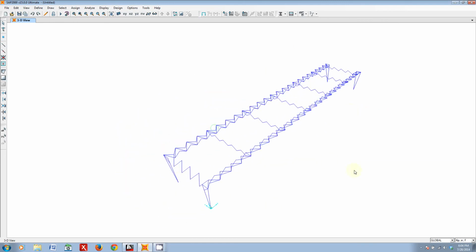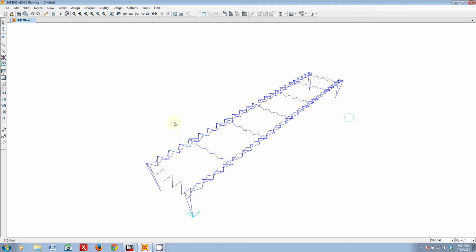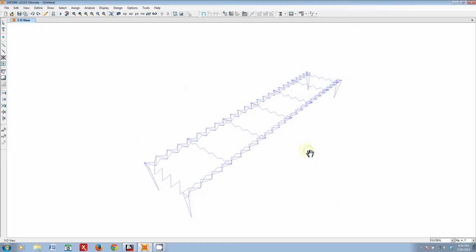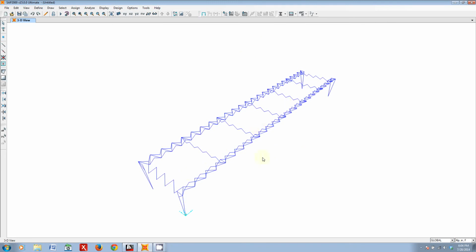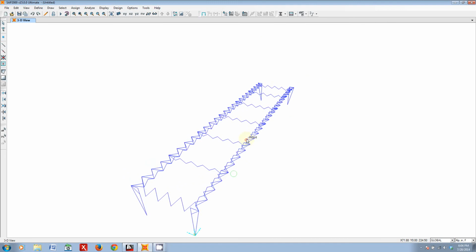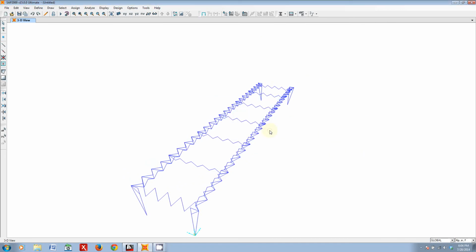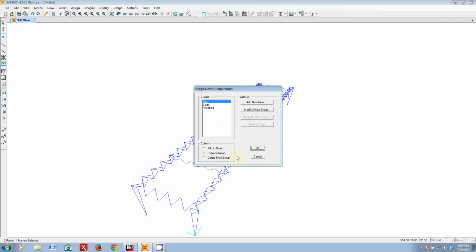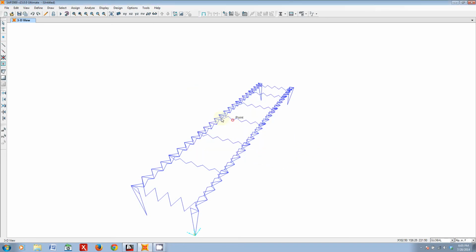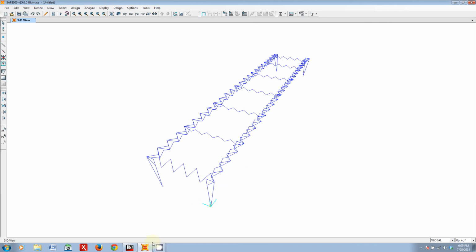But I will upload the final completely imported file into the Dropbox, so you can take a look at that and maybe compare it. And hopefully also I would encourage you to go through this exercise, get used to using Control G, the select groups, and the Control Shift G. Mind you, you have to have something selected to be able to press Control Shift G. That's an important note. Get ahead and start practicing with those, and hopefully you'll be a master in no time.